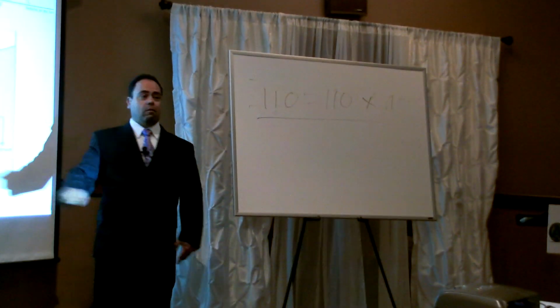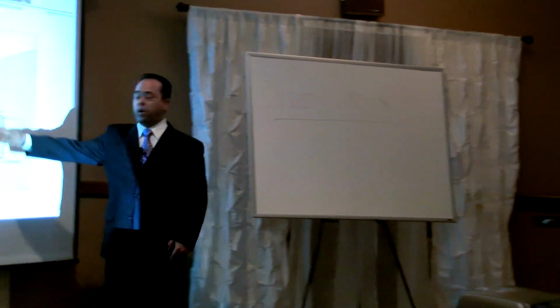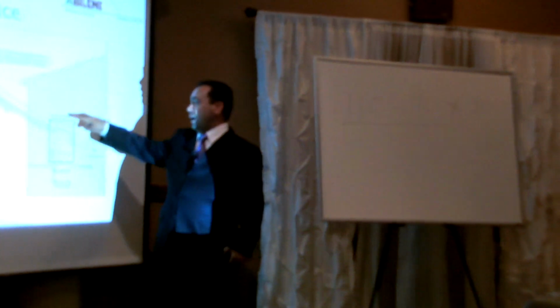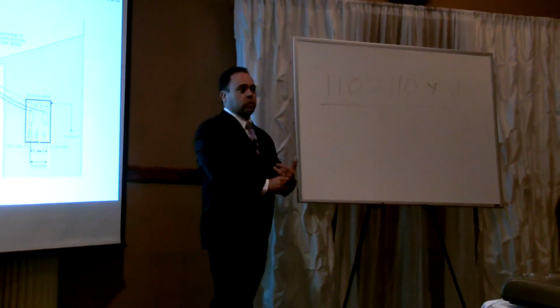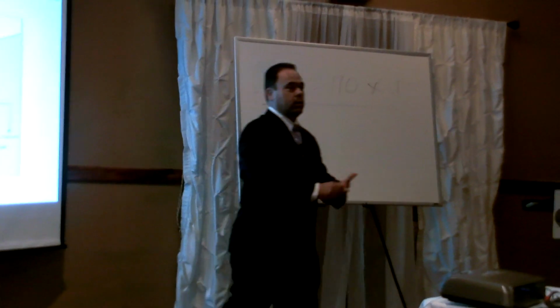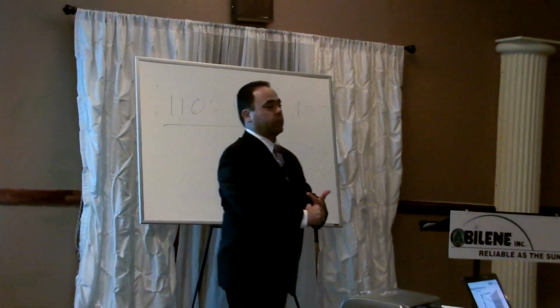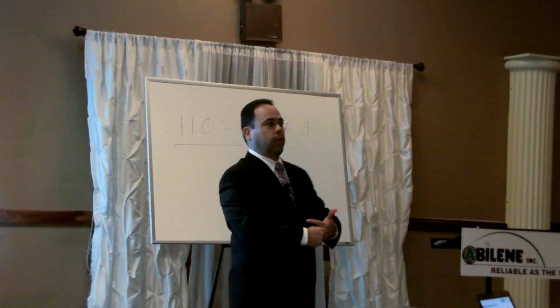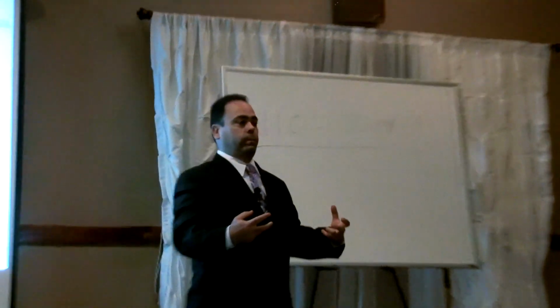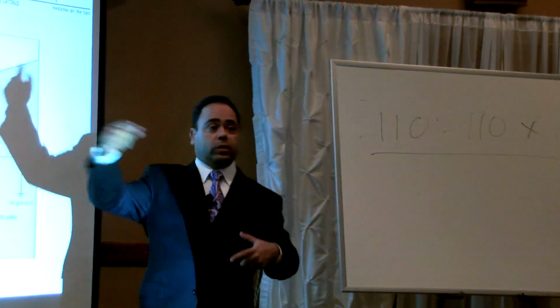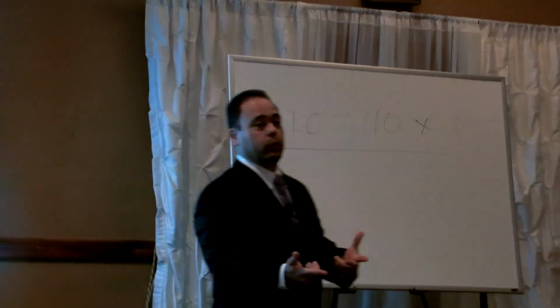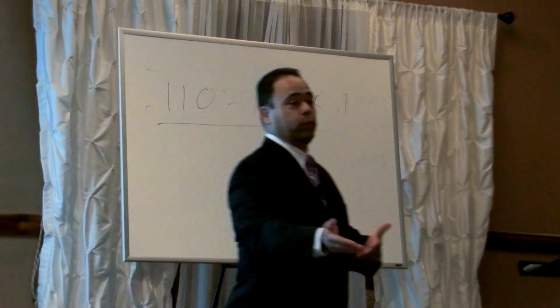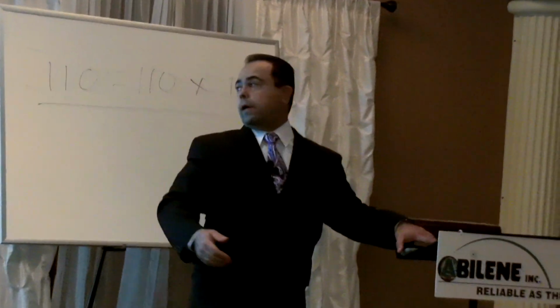Neutral is not ground. Neutral is part of your circuit. Ground is your box, your ground wire, your conduit. Okay? It's protecting that system. And with that, we're going to go into the next step. It blows your fuse or activates your fuse or circuit breaker. Okay?